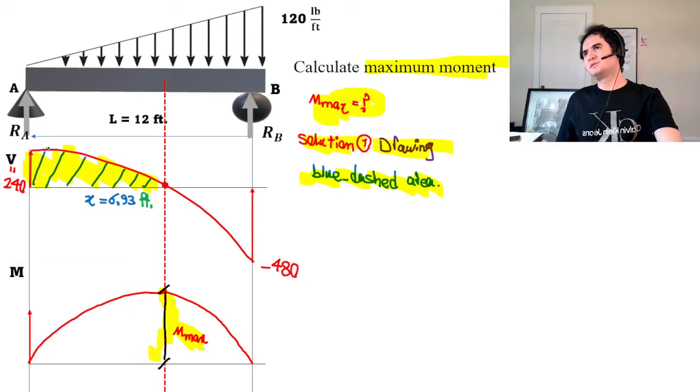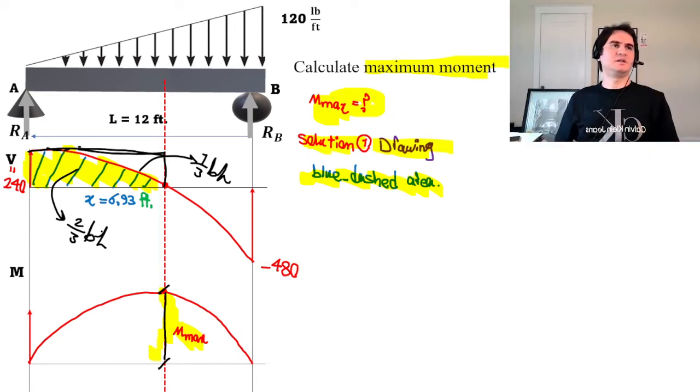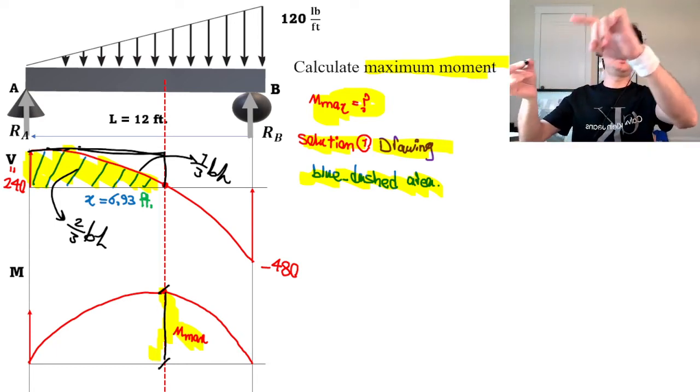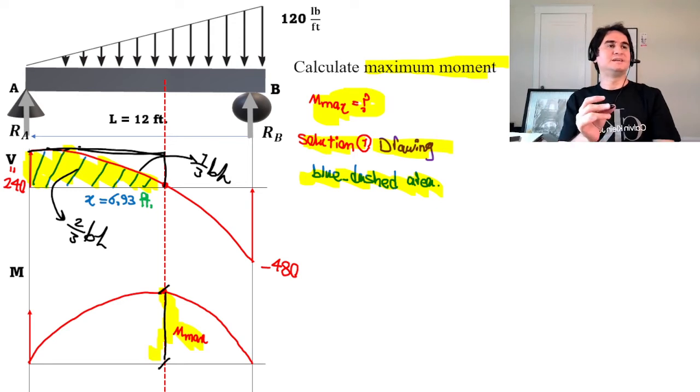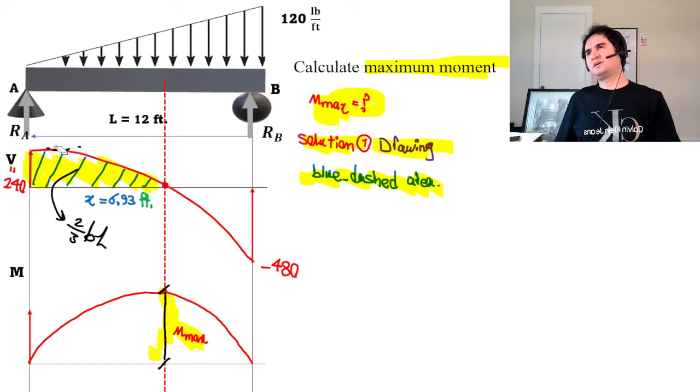So if we know from a parabolic spandrel, which is this one, that it goes by 1/3 of BH, the other goes by 2/3, because the two areas together consist of a rectangle with B and H. If this is B and this is H, and this is 1/3, the other should be 2/3. So our area is 2/3 of B times H.